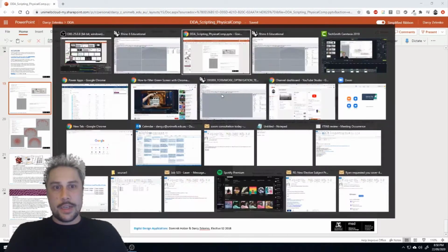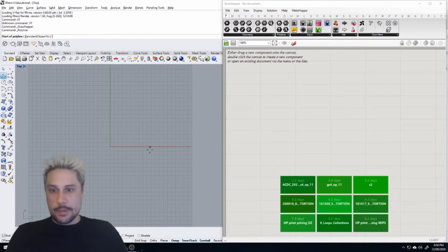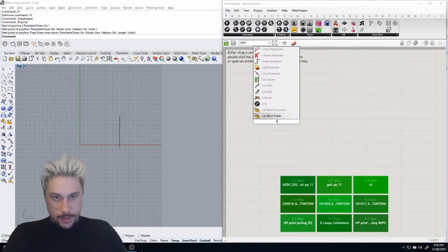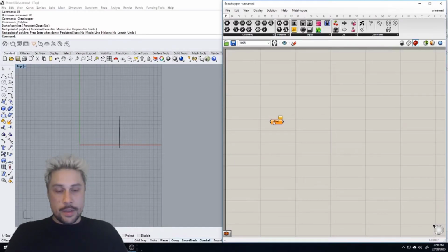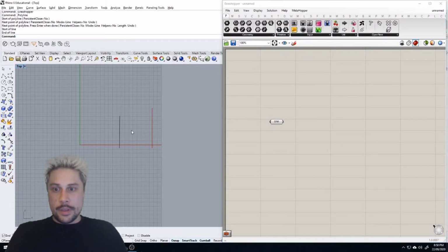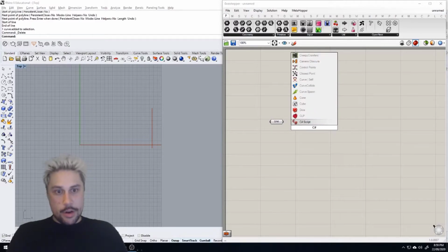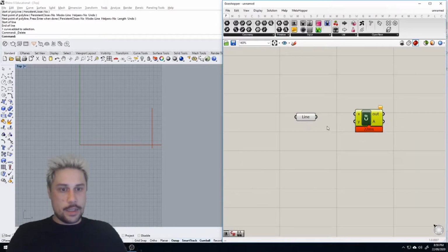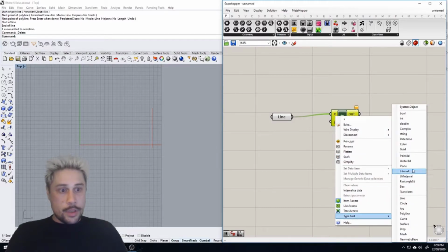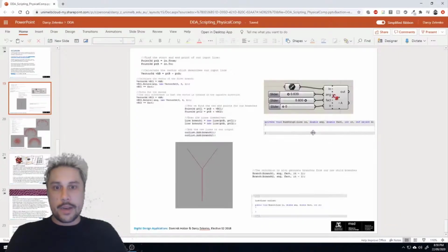So we're going to need to open up Rhino and Grasshopper, and I'm just going to draw a line. Oh, maybe I'm not actually. I might just reference it in. We'll see. Set one line. Cool, and we're going to drop a C# component onto the canvas because we're going to be writing it in C#. And we'll hook our line up, and we will give it a type hint of a line, which is very important.